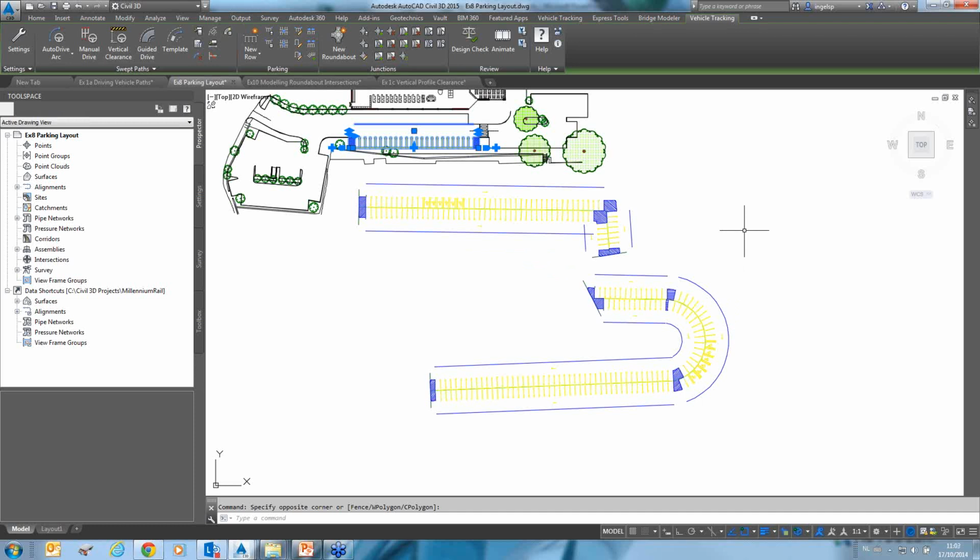Yes, there is one according to the roundabout, and it's: can you make an S-curve before you go into the circulation? In Sweden we have that. Not at the moment, and that's why we say it's a preliminary roundabout tool. If you want to do the S-curve, what I would do is start with the roundabout tool and then modify the geometry and update it manually. That's how I would do it. But the complete S-curve before the roundabout is not possible in one single click, basically.